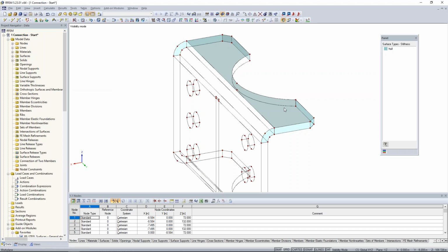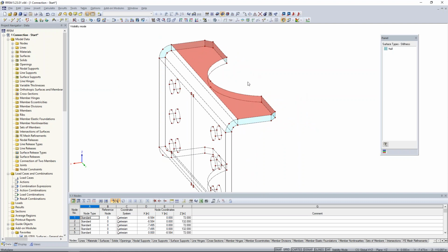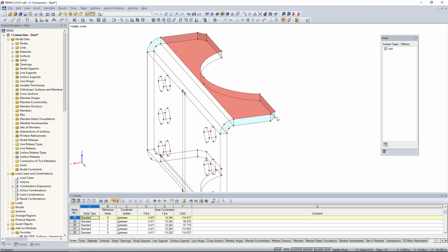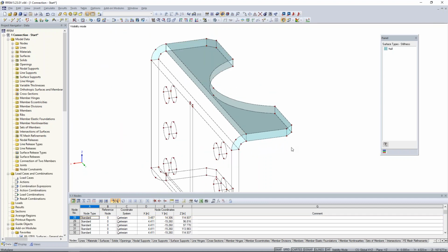And we'll actually utilize these curved surfaces here on the side because these are in a single plane still, and we are done. So this top surface, I need to copy it down to my bottom. So I will highlight it, hold down my control key, and then I can actually just drag and drop and make a copy. And you can see I kind of am slightly off there. No worries, we'll hit the undo. Can zoom in here, drag and drop, and let's try and snap that to this point here again. So now we have that null surface shown on the bottom.